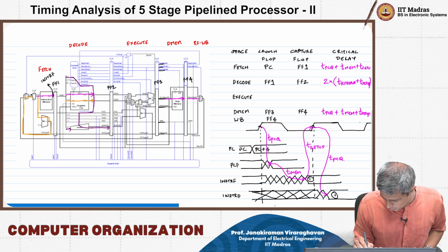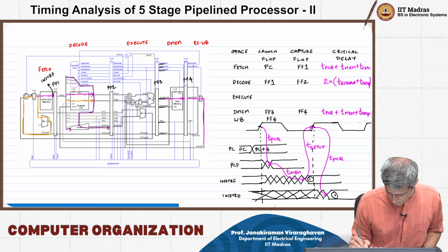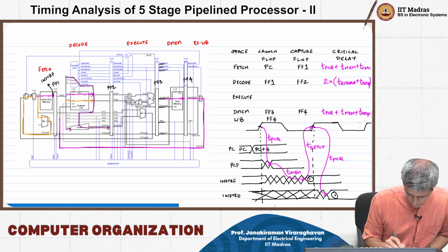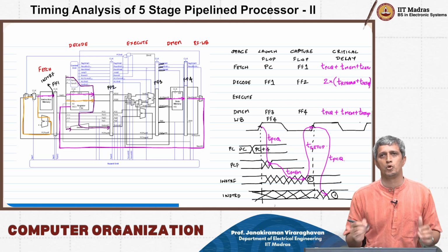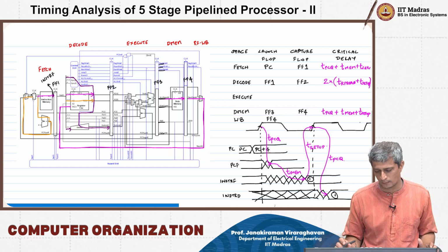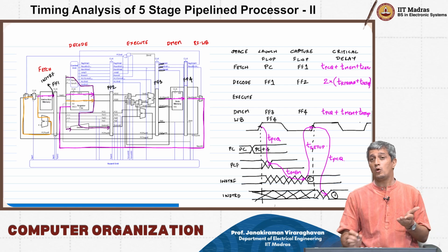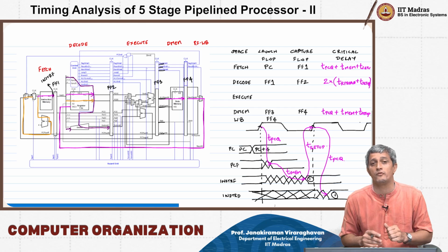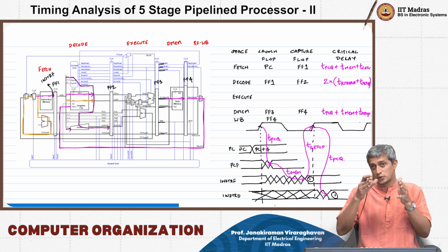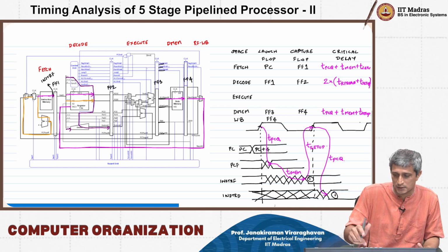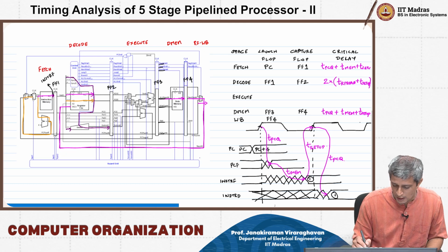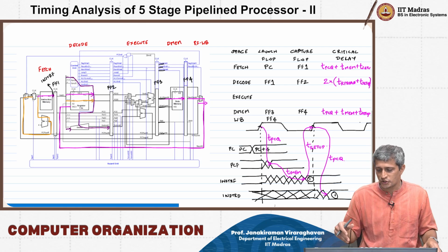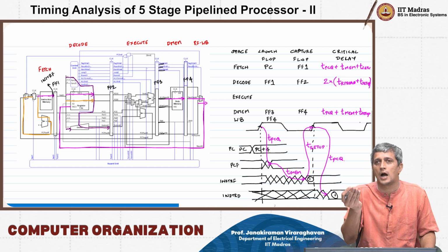I can start here, you go through the mux, right? The data can come all the way like this to my WD3, because you are trying to write back to that register. Now what do we know? We also know that this write back has to happen on the negative clock, and therefore this whole operation of T mux, so this is a T mux delay, and you have to come and write back into the register, right? So that operation has to finish within half a clock cycle, right?